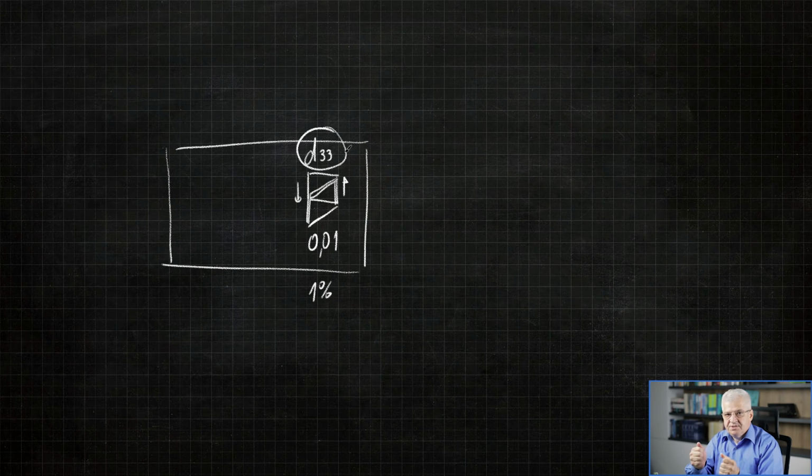If you use the compression only 2D members, then the solver is also using orthotropic properties to reduce the stiffness in the main direction of the main axial forces, and this is done with orthotropic properties for each element.